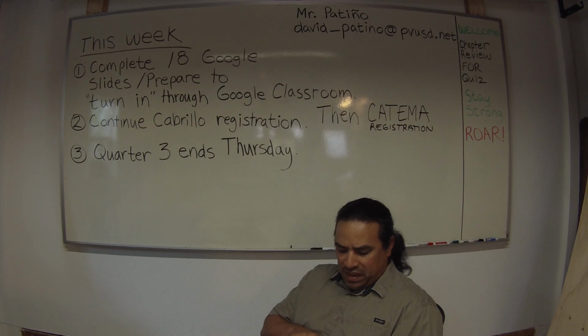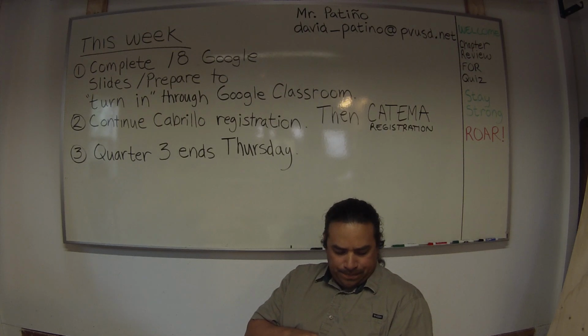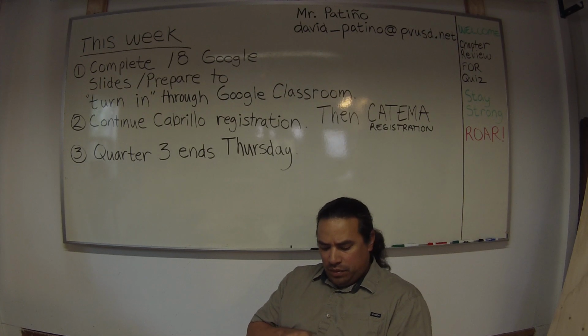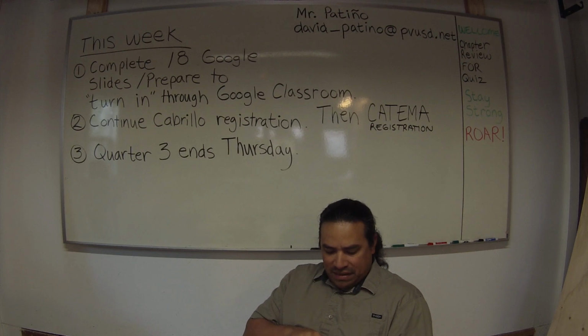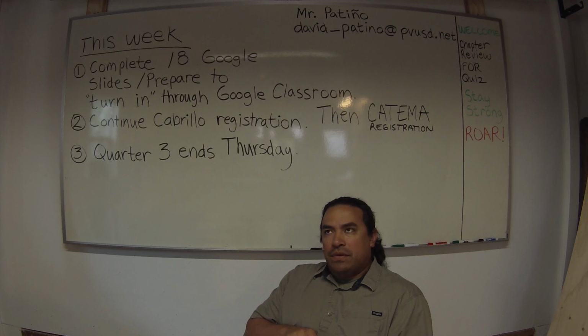Next section, equilibrium and moisture content. A piece of wood will give off or take on moisture from the air around it until the moisture in the wood is balanced with that in the air. You could consider wood a type of sponge. It's always trying to absorb water because it was originally filled with water and sap.